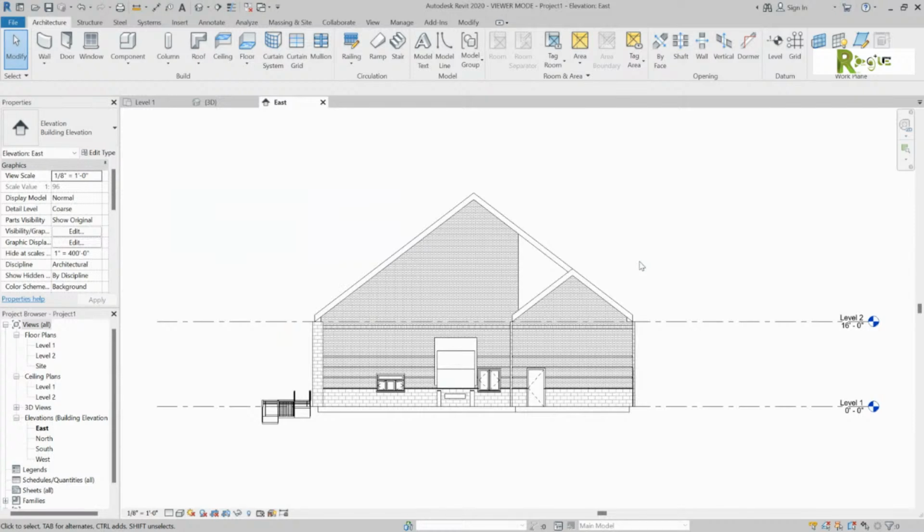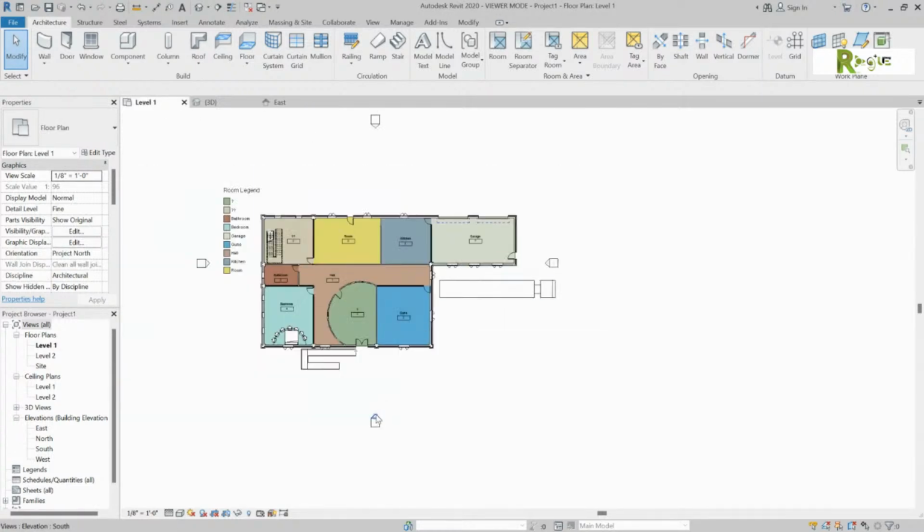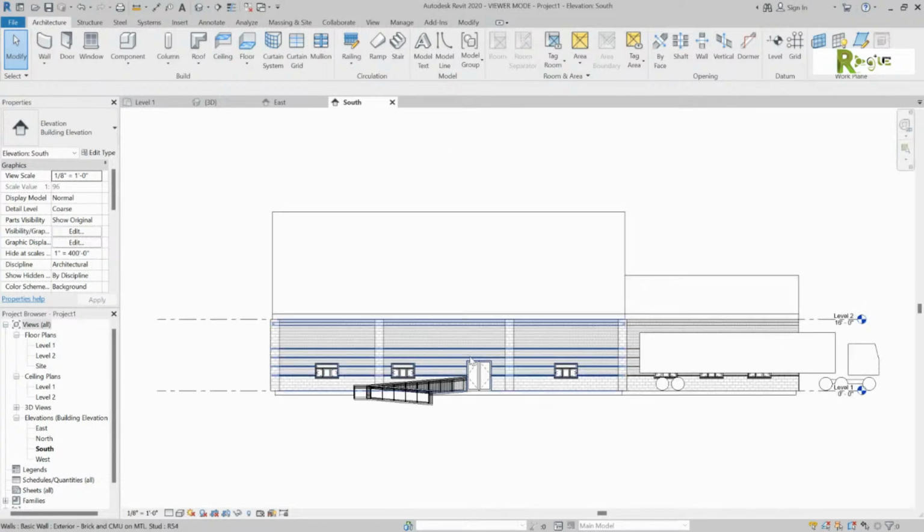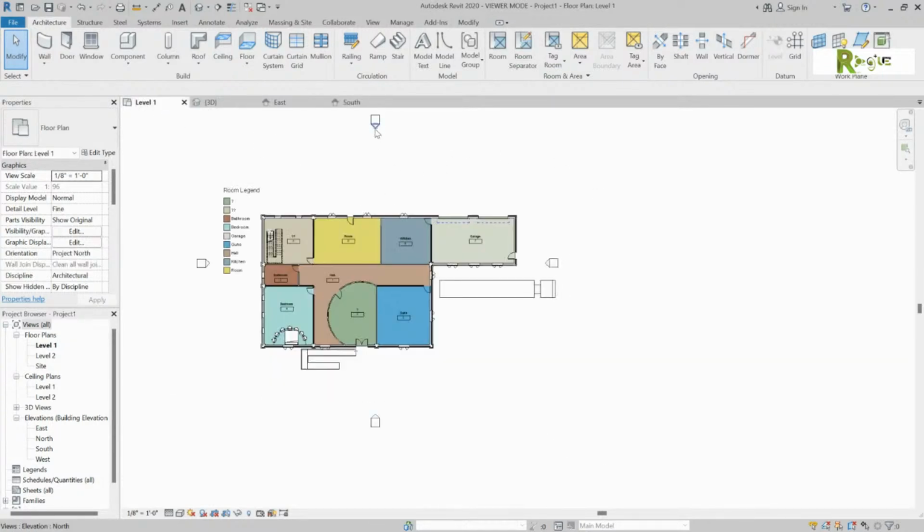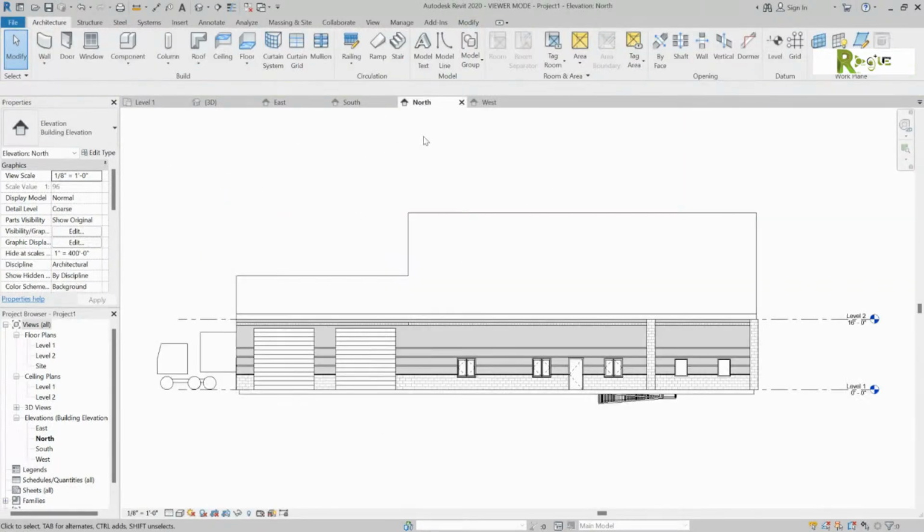If you went back to level 1, you did the one on the bottom, it would give you what, the north or the south elevation? South elevation. So that's the one looking towards the front of that thing. If you notice now, when you're in one of those views, your levels work. Now, a second ago, I said you draw your levels first and then your grids, and I'm going to show you why. Go back to level 1